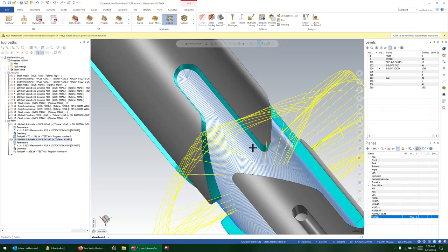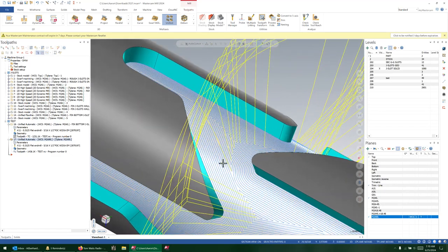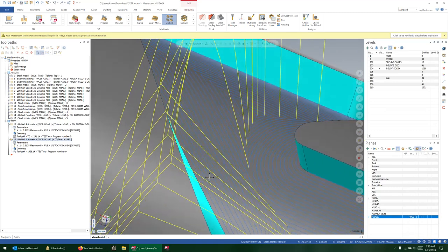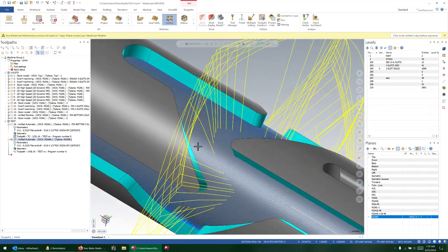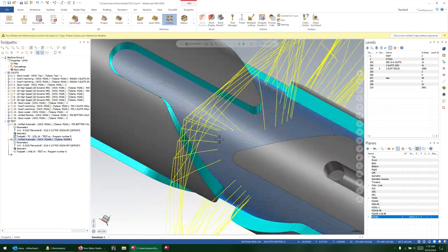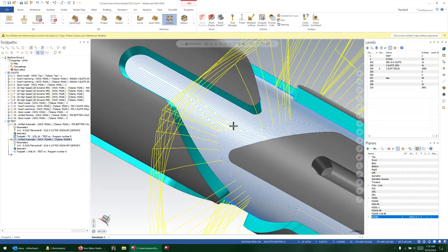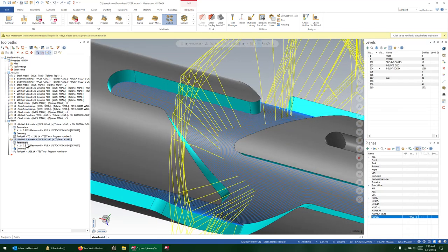The best you could hope for in this one would be to trim off anywhere that it touches the corners, but you're going to find yourself in some weird situations where it's trimming off half of this pass, but not a bit of the other one, because of course it's all just a tolerance thing. It would be better if we could just avoid it as part of our pattern, and luckily we can.